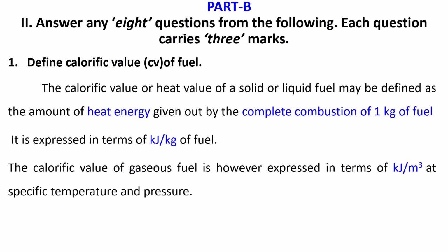The calorific value of gaseous fuel is, however, expressed in terms of kilojoule per meter cube at a specific temperature and pressure. That means the calorific value is the heat energy produced by the complete combustion of the unit quantity of fuel. If it is a solid or liquid fuel, then it is kilojoule per kilogram. If it is a gaseous fuel, it is kilojoule per meter cube.